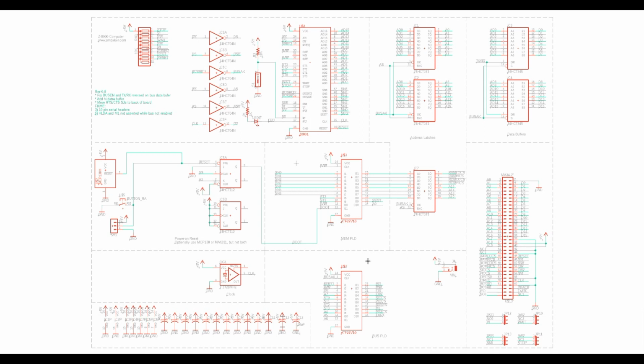It's also got down here a couple of programmable logic devices where I implemented some logic. This one here does segment translations. This thing supports up to 127 different segments. Plus, it supports separate instruction, data, and system normal. We don't use those fancy features, but we do use the segments.